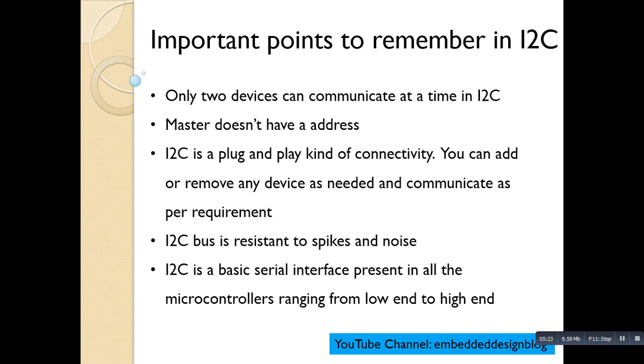Now this is very simple and you don't need any additional configuration. What you need is a slave with a specific address. Once that slave is connected, the master communicates to it. Now in future if you want to add any slaves, it's very easy to add onto the bus. The only thing we have been talking about is the capacitance and hence the rise time that is associated. Otherwise the master can go on adding slaves to the bus.